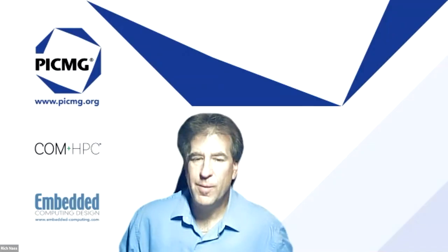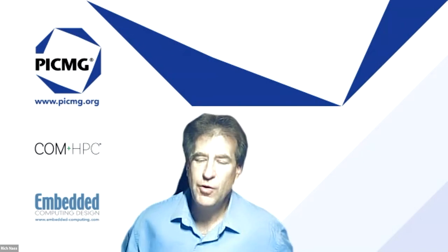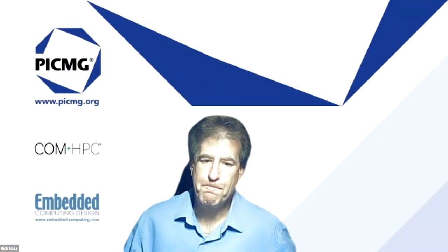Thank you, Henk. That was really informative. One thing that I did want to ask you, though, I haven't really heard it come up. Do you expect COM-HPC to be used in any harsh environments? Yes, we do. Of course, if you go to server level, it will be around -20 to 70. But definitely on the client side and the server side, if we use low power silicon, it will also go into the -40, 85 rugged designs. But with high power, we will have to step up on enclosures. I do see water-cooled enclosures coming up in this area.